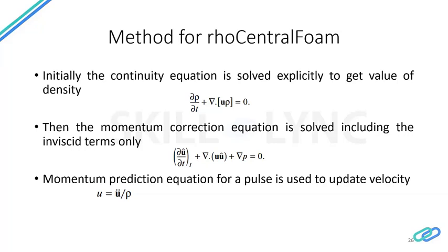Initially, as I said earlier, in meshing, the geometry is discretized, and the cell centers or the face centers are taken as the coordinates. On these coordinates, the field variables, your density, temperature, velocity, are all mapped, and these are set into matrices.